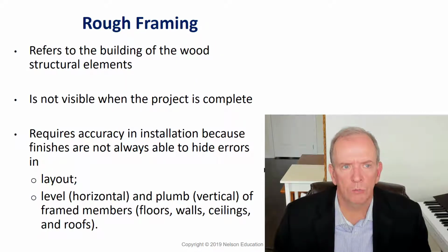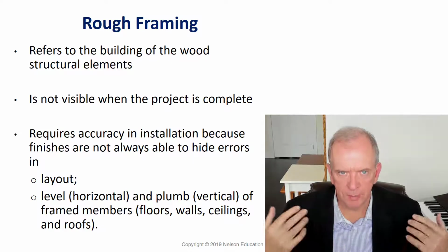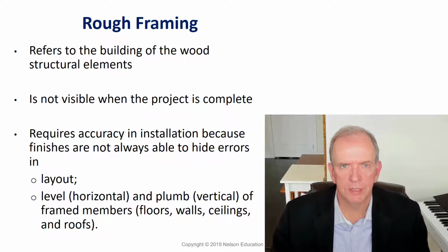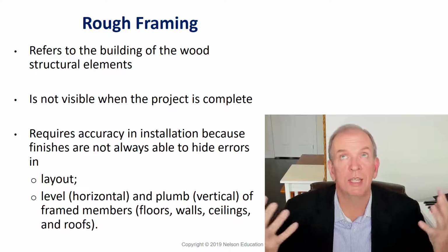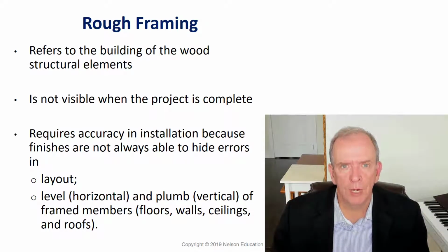Some people will refer to it as rough framing. I'd say that's getting used less and less these days. They'll just say framing, but the rough idea is when we're using stick method, platform framing, like we discussed in the previous lecture, it's hidden when you're finished. So unlike timber frame construction where you'd want to see the exposed beams and posts, wood frame construction is hidden.